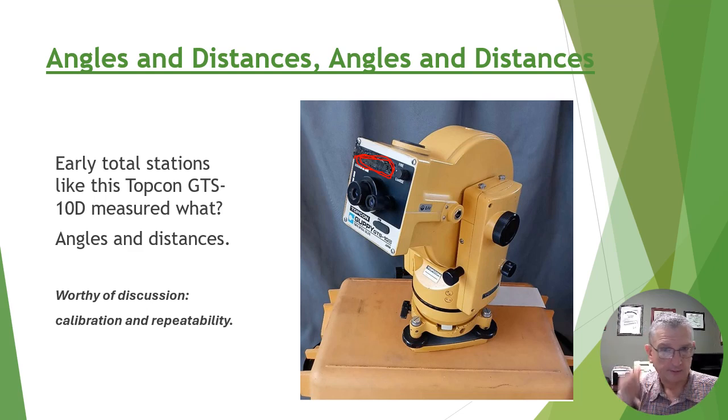This guppy is nothing more than a manual theodolite. On the other side of the instrument, if you're looking at the picture, was a little door that opened with a mirror where you could reflect sunlight into it, and we would read the angle off of a vernier manually by dialing this vernier knob right over here. We would fine tune the horizontal and the vertical angles with these tangent screws, and then we would line up the crosshairs on the vernier looking into the side of the instrument to get the horizontal and zenith angles to record in the field book.